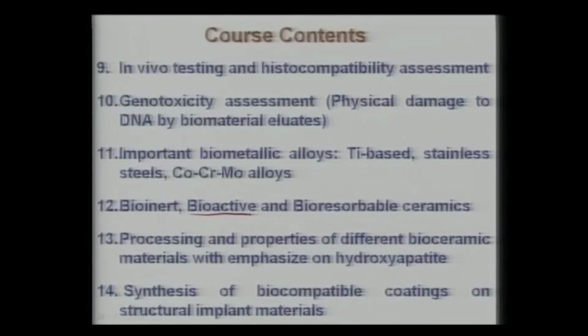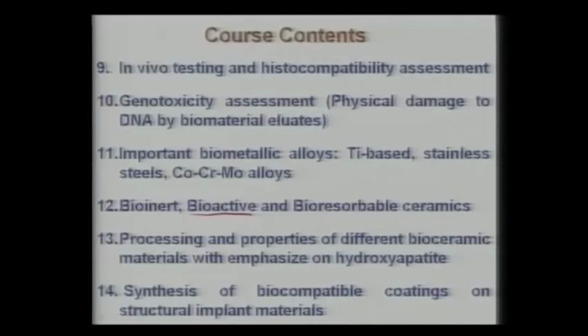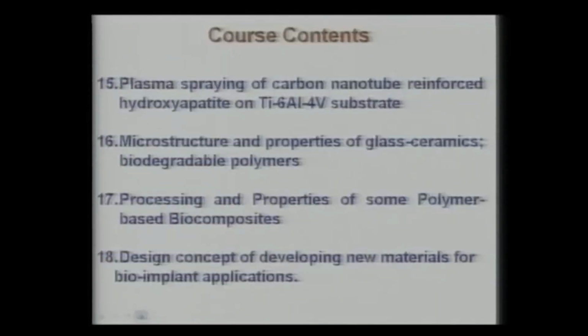Then synthesis of the biocompatible coatings on structural implant materials like hydroxyapatite coating on titanium or stainless steel, how they can be processed, what are the properties of these hydroxyapatite coatings and so on, that will also be discussed. Now, plasma spraying of the carbon nanotube reinforced hydroxyapatite, that is the specialty of the other colleague Dr. Balani, who will be taking some lectures as part of this course.